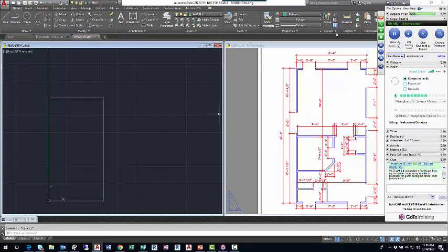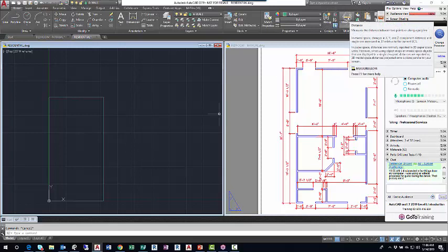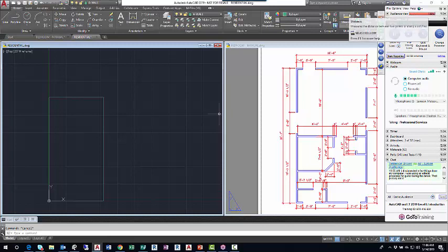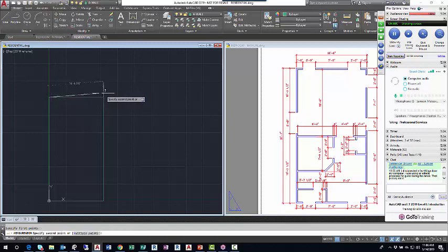You can also do this. We used that distance tool yesterday, that yellow ruler icon. If I wanted to, it's a little more involved, but I'll left click on distance, move my crosshairs into my drawing window, specify first point, I'll left click the upper left corner, left click the upper right corner, and there's your 16 feet 6. I'll click distance again from the drop down menu, left click the upper right corner, left click the lower right corner, and that's the result there. So that allowed me to measure the X and the Y, the horizontal and vertical of this.